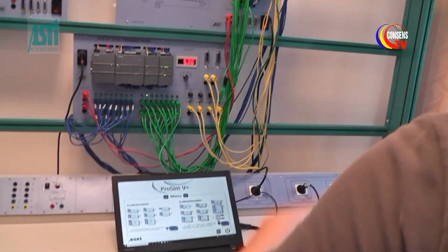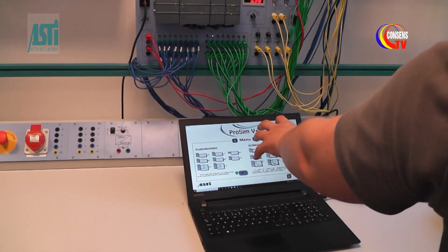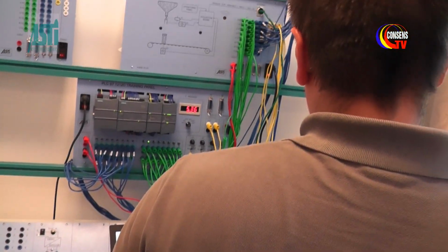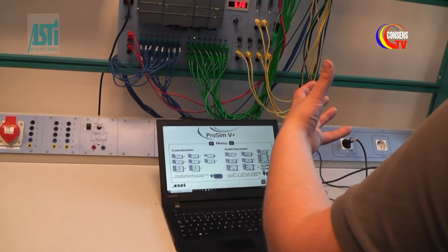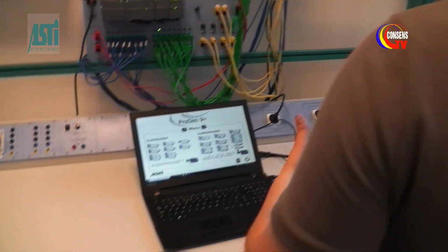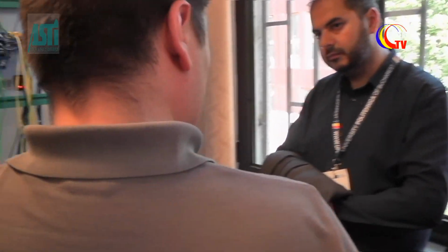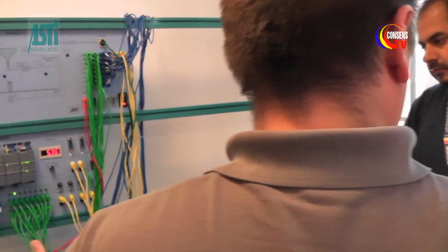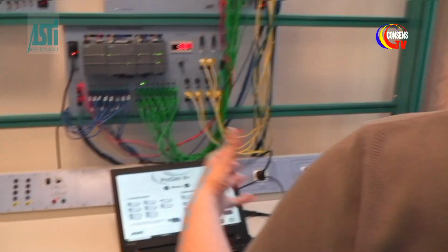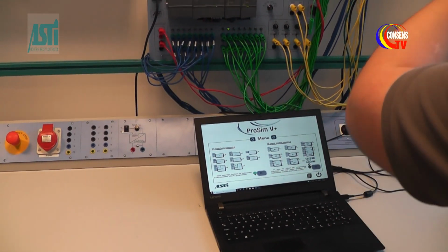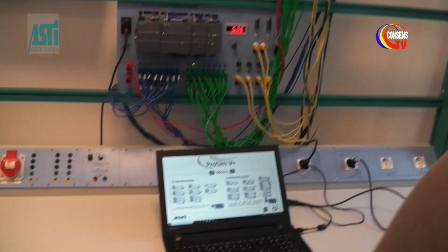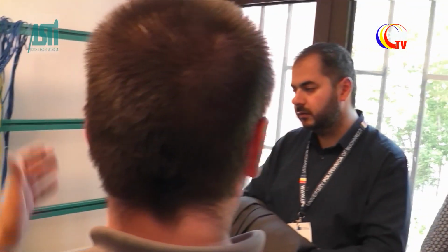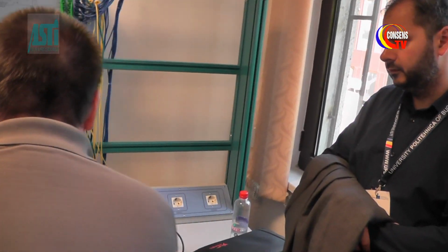Yes, but like I said, here we're not doing process modeling, and we don't have MATLAB here. This is more intuitive for the students who learn discrete systems, not continuous systems. So you saw the temperature, but you don't have a PID control or a model like this. You have just some levels, and if it's below a level, start; above, stop. And if you have the software here, this will also work in the real environment.